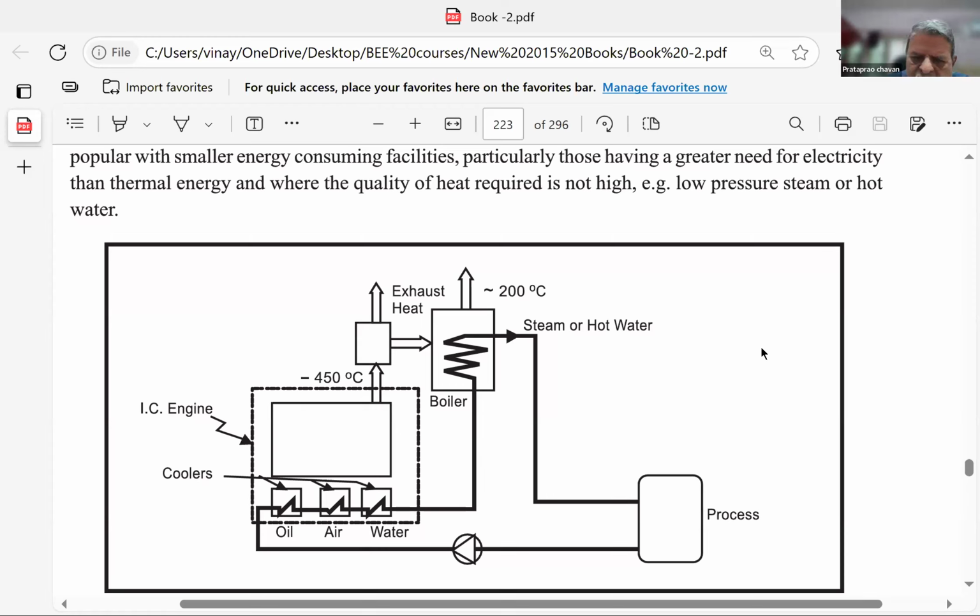That's the process. Okay. Remember that whether it is a pulverized boiler or a cogeneration boiler or fluidized bed boiler, the boiler exhaust temperature of the gas is restricted by the pollution control board. Why? There is a reason. Because you will say, why should 200 degrees heat also be allowed to the atmosphere? Why not extract it further so that we can bring it down to 100 or 80 degrees and then allow it? We are wasting this heat, isn't it?